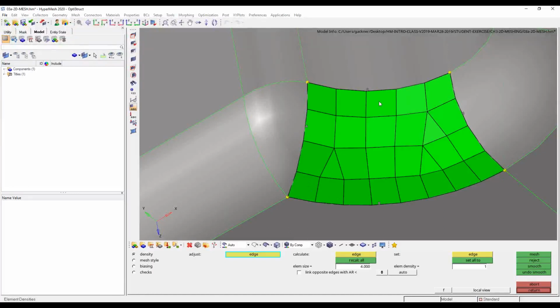Now we have a couple options here as meshers. I can either leave it exactly how it is, and the benefit of doing so is that I'm ensuring the elements are as close to the same size as possible. And frankly, that's something that I'm a big fan of doing. Now I could also adjust the element densities though, and it might resize the elements a bit, but it can help ensure that I have a clean quad dominant mesh.